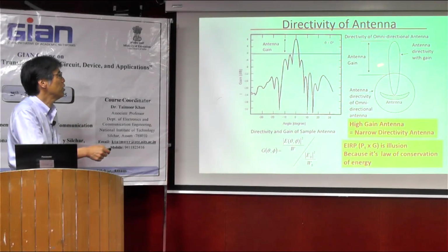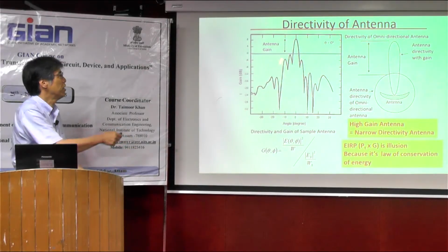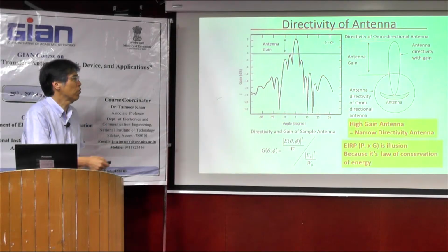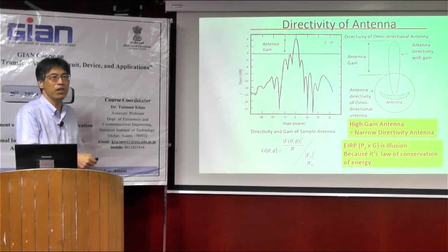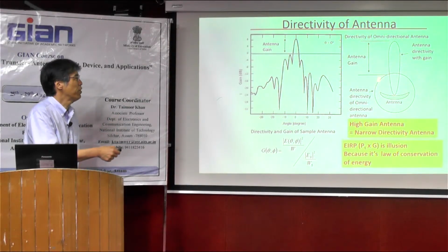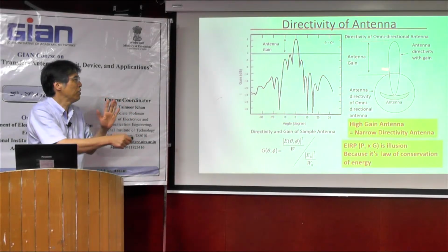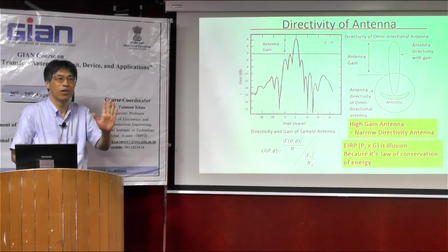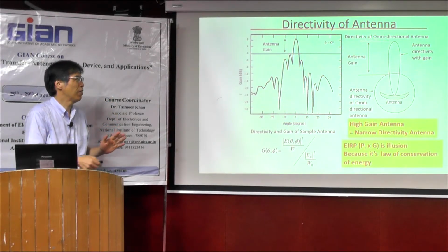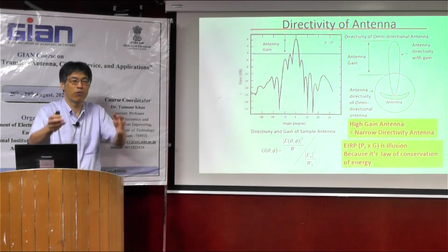So if we have a large antenna and antenna gain becomes high, directivity becomes very narrow because we transmit only 1 watt. So please consider this directivity when we would like to develop the energy harvester. If we have a large gain antenna, a large size antenna, we have to face this directivity to the source itself. So it seems it's not convenient, because hopefully we would like to gather all directional waves from everything.